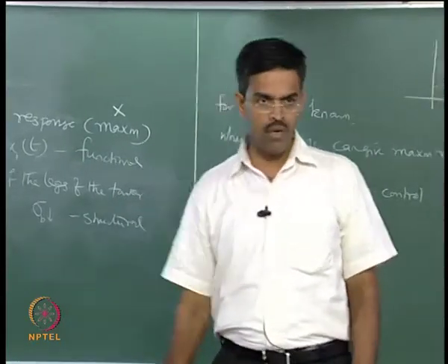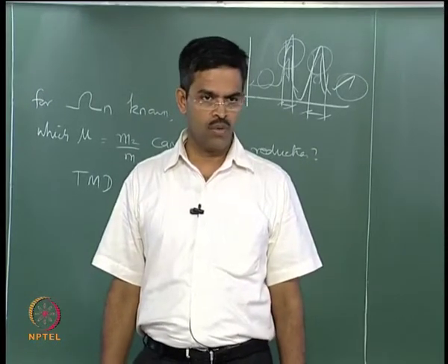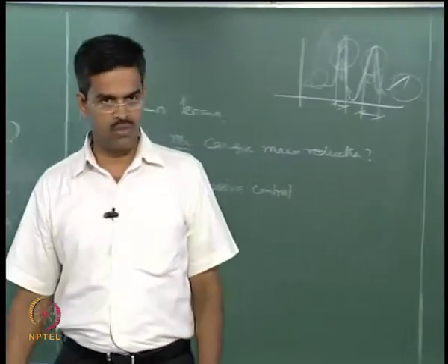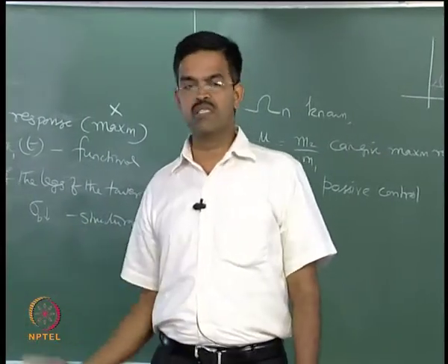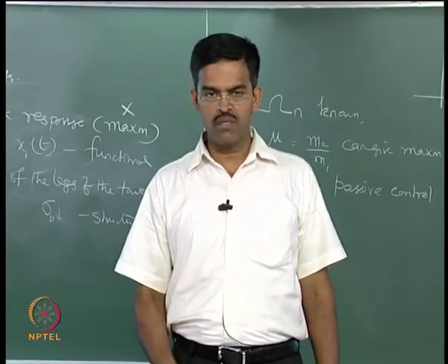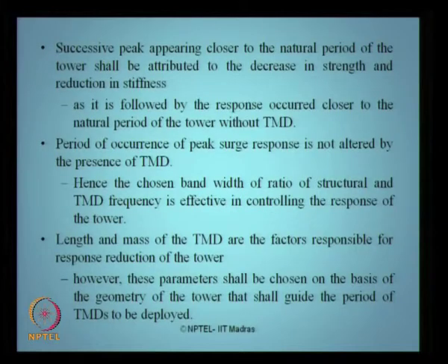It all depends upon the mass ratio with respect to the tower, that is very important. So, they cannot be generally applied to all kinds of platforms. That is why the whole exercise is attempted: tuning the secondary mass for damping the response of the primary system. That is one of the passive techniques deployed in this study.